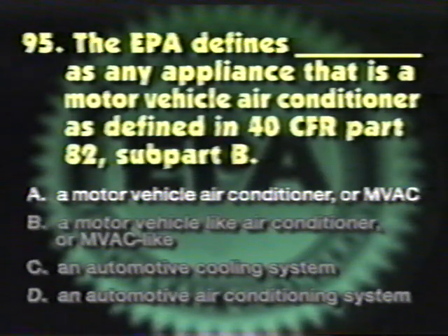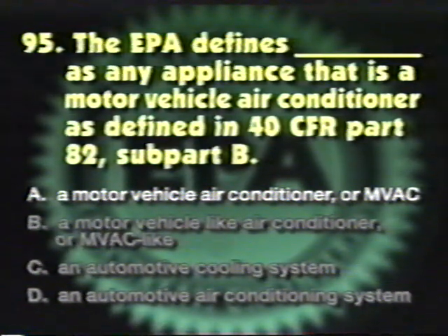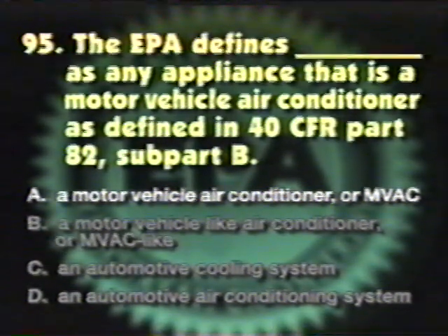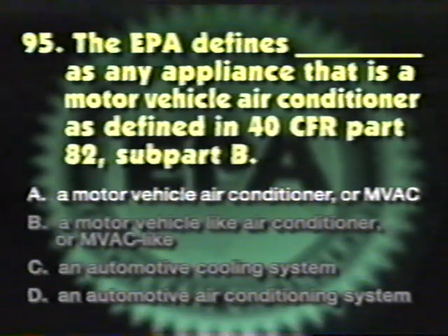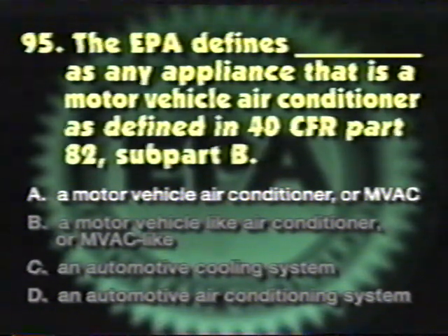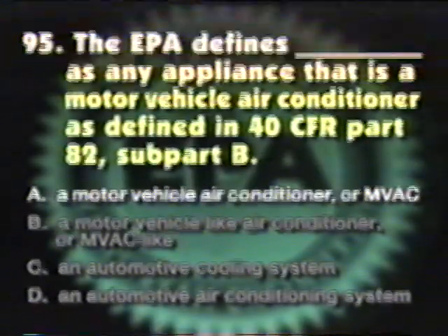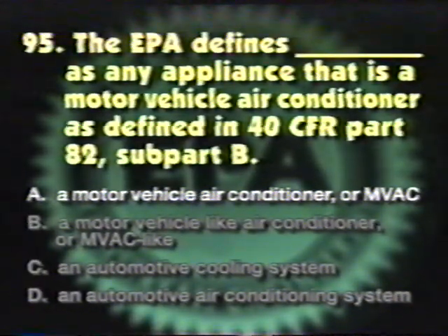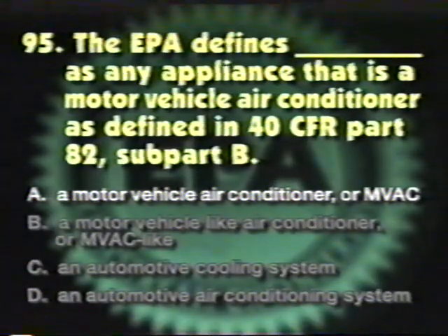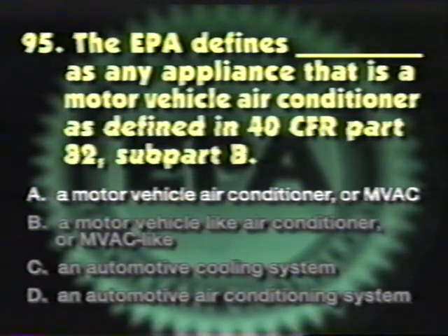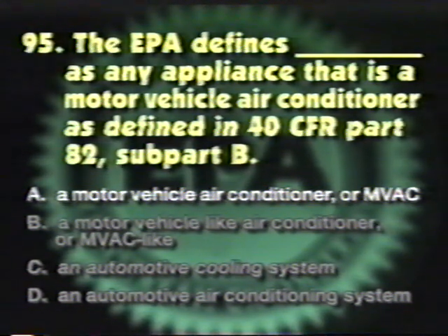The answer is A. The definition of motor vehicle air conditioners, or MVAC, is mechanical vapor compression refrigeration equipment used to cool the driver or passenger compartments of any motor vehicle. This definition is not intended to encompass the hermetically sealed refrigeration system used on motor vehicles for refrigerated cargo or the air conditioning systems on passenger buses, which use HCFC-22 refrigerant.